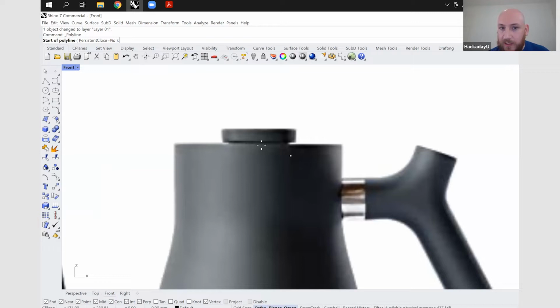So I'm really going to do a revolve in a minute. So I'm just interested in half the geometry. I don't need to go further than that. I do want to make sure that endpoint is selected. Just hover over and get that endpoint. Go past the curve.